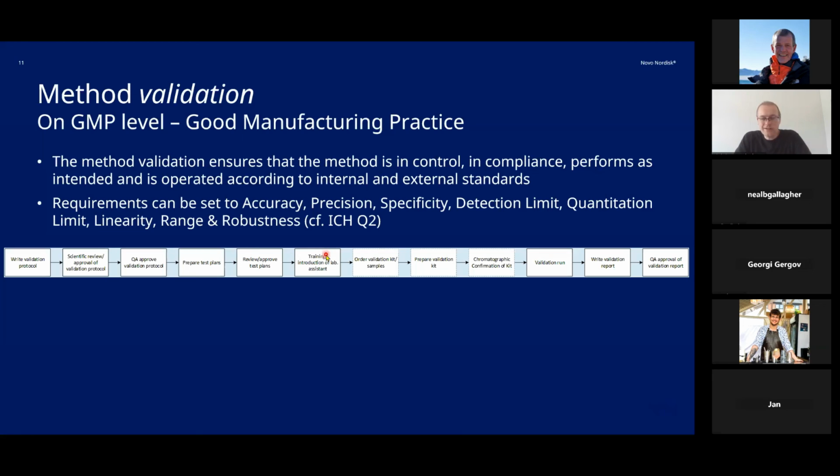So, for instance, getting an assessment of water content is notoriously difficult because the analyte is all over in the air. So how do you ensure that the sample you measured on your at-line method, that the water content does not change while taking it out of the instrument and into the lab for Karl Fischer water determination?